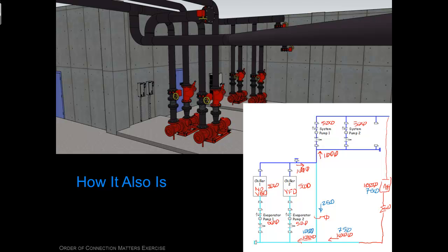But not exactly. Okay? If you'll remember, the whole reason, we think at least, this machine had a VFD on it was because we wanted this machine to see the load variation and this machine to always run at full load when it was online.